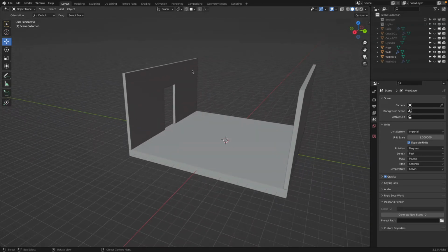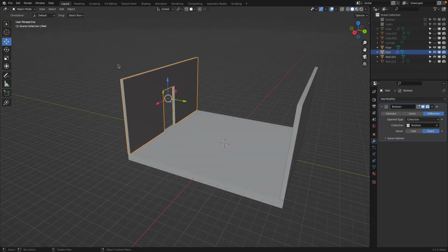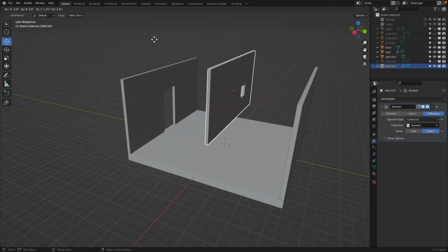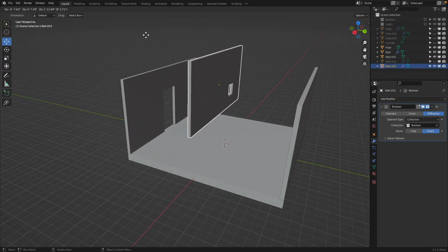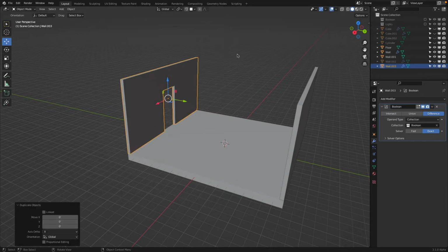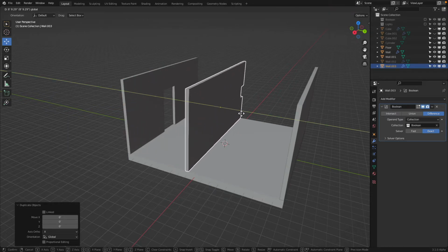Is there a different way to do this? Yes, there is. So here's actually the object. And I can go now and say, just make me a duplicate of this object. So it's kind of like a copy and paste, just as one command. And it's Shift D also, the key shortcut. So click, and then when you move your mouse, you see you're instantly in move command. So what I very often then do is I press the escape key or right mouse button. Then the object is just inserted. I have two pieces there right now.